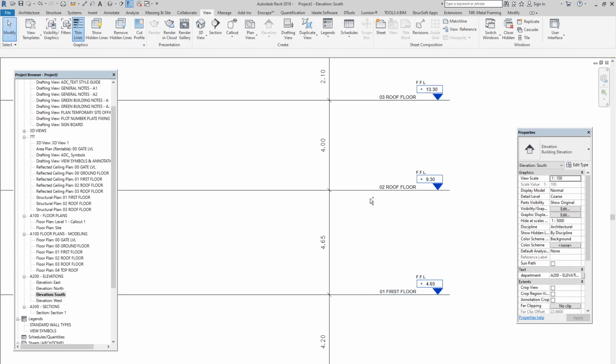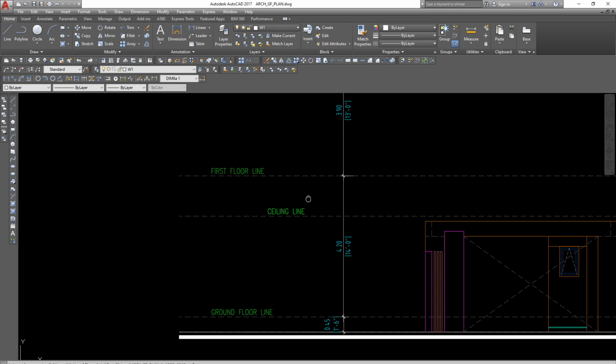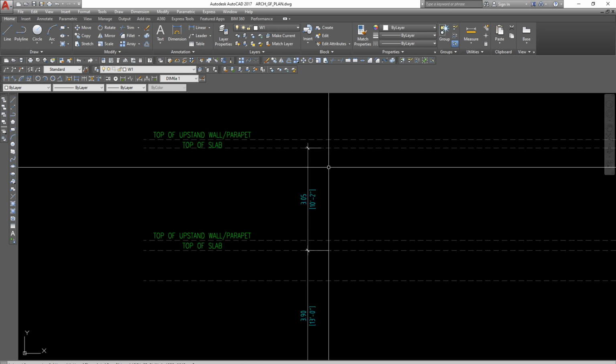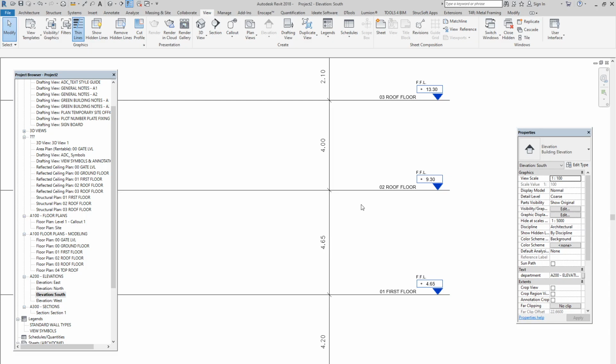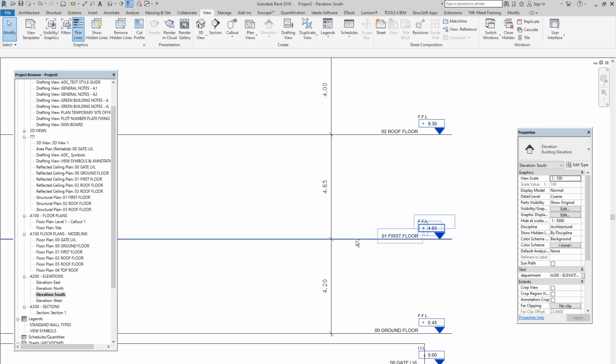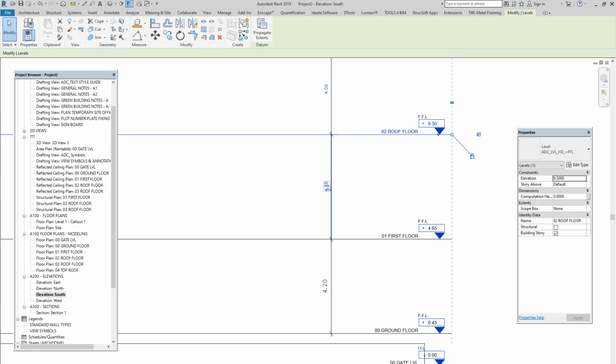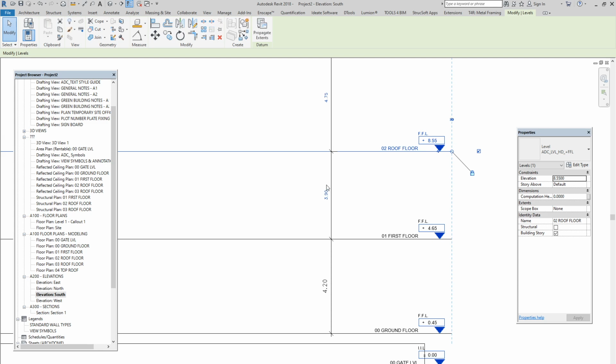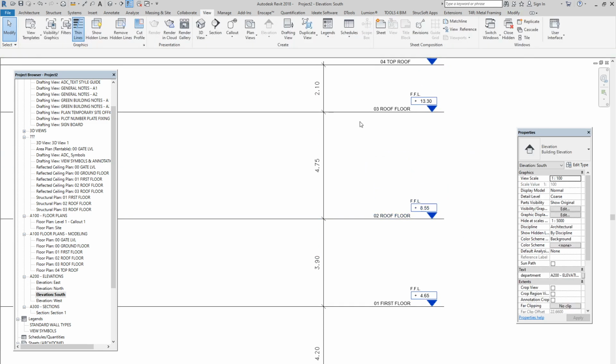So start now. This is fixed. The other one which I want to create, I will just double check how much the size is. 3.9, after this 3.05. Okay, so now here we will go back from the first onto the roof, 3.9. So I will select the movable, it will become the temporary dimension, just select it and type 3.9. It will edit the space, and from here also 3.05 as we agreed.